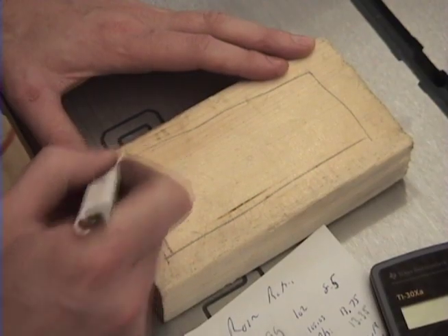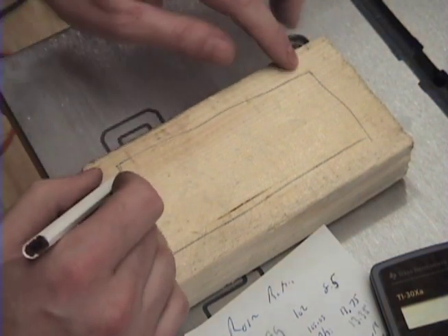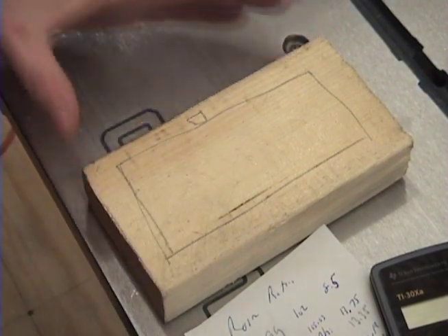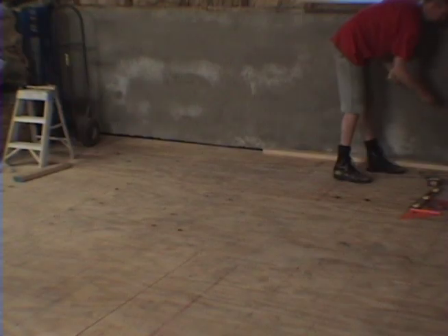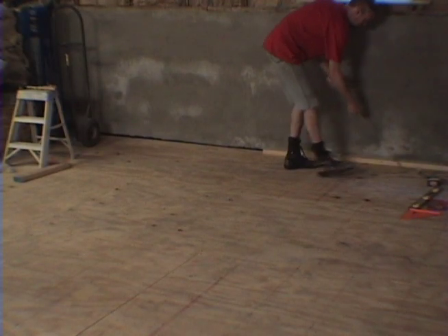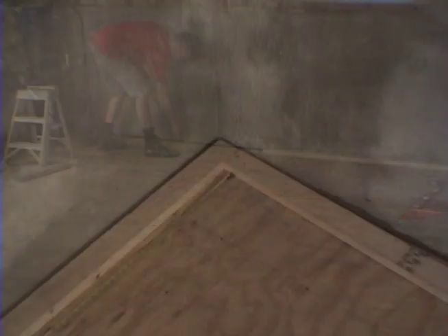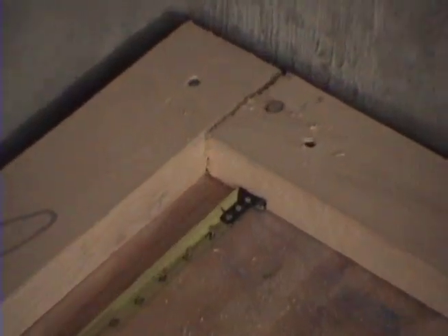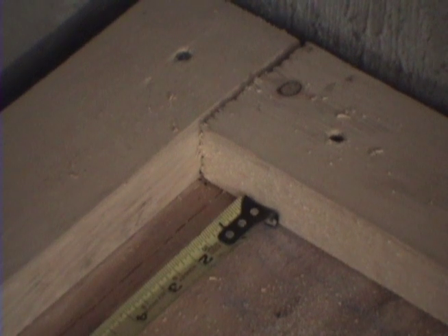The left and right walls of the control room are supposed to be angled by 3 degrees by design, but I have a support pillar that cannot be moved right here. The actual angle of the left wall will be determined by that pillar. If you don't have restrictions, just measure the angle and build the bottom plate out to the front wall mark. Hold in place with a few screws, but don't put them in all the way just yet. We need to make sure everything works first before we fasten it down permanently.